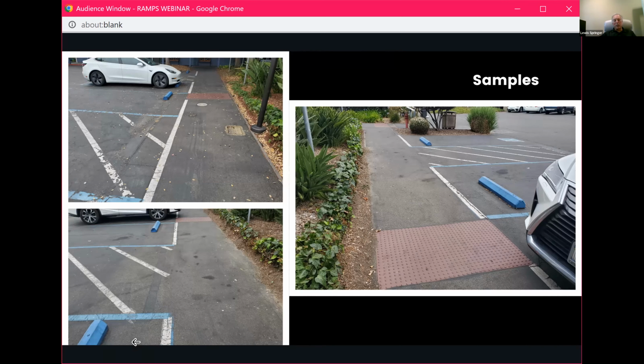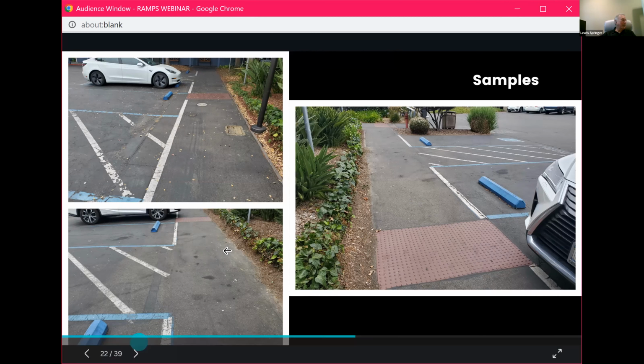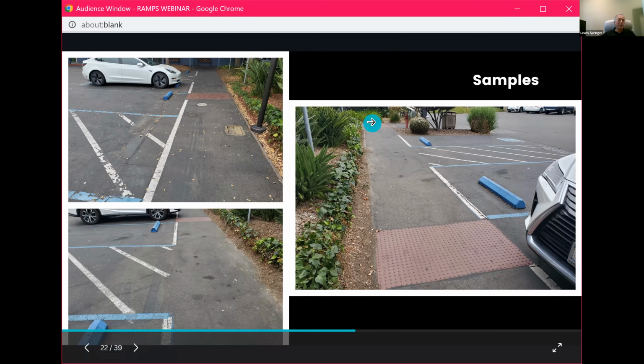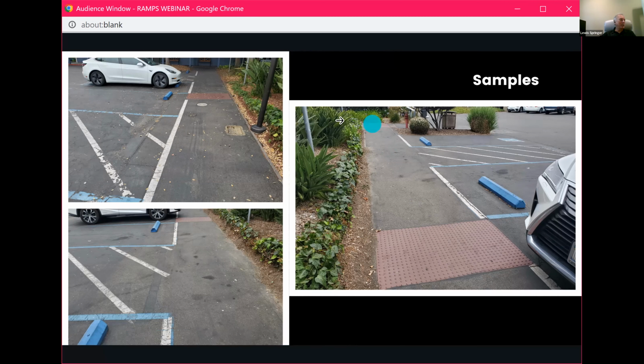So I ran across this a couple days ago. Here from this point, see that? There's a walkway that goes from that point all the way to the end of the walkway at this point. So I've taken pictures in both directions. I'm quite confused as to why the detectable warning is placed where it is, because if you are visually impaired and you're walking along, coming across this detectable warning is supposed to clue you in that now you're going to enter a vehicular area.